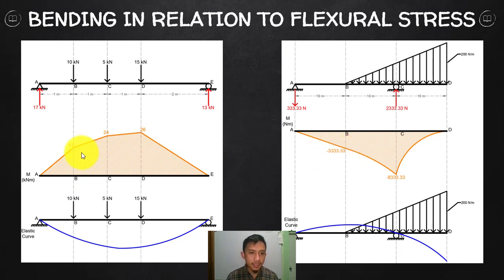Now again, if that is a positive moment, then this entire beam is opening upwards, which is true since that is the type of loading. So that will only bend opening upward, since again you have positive moments here. And then here, negative moment. So that means your entire beam will concave downward. So this is your deformed shape.